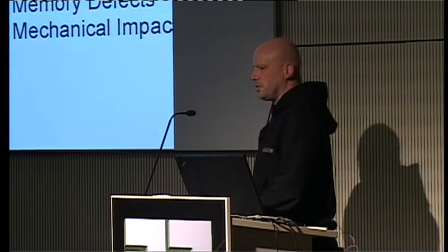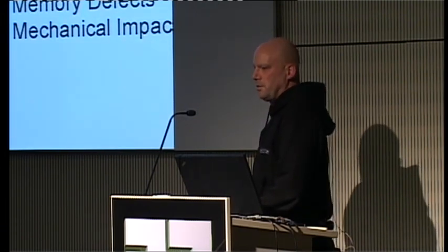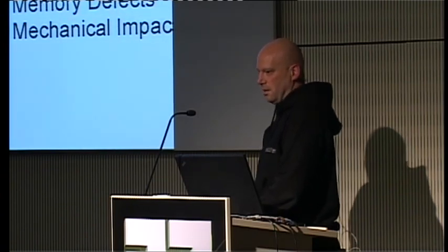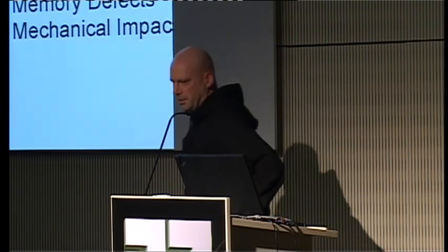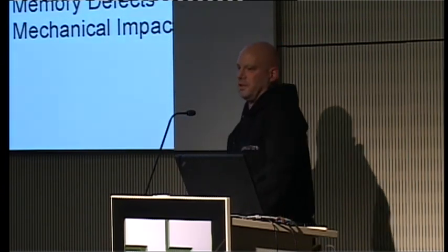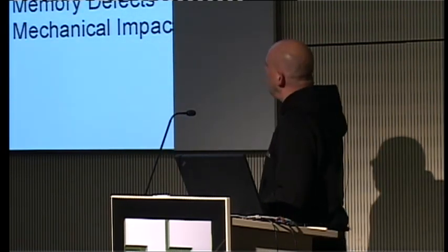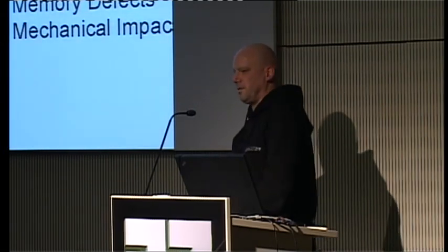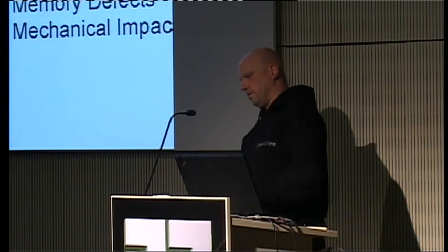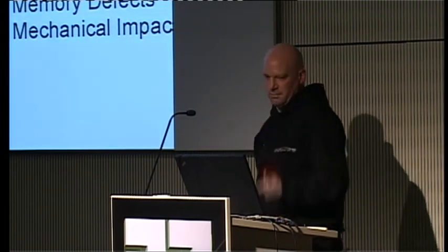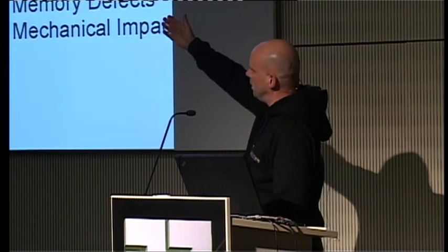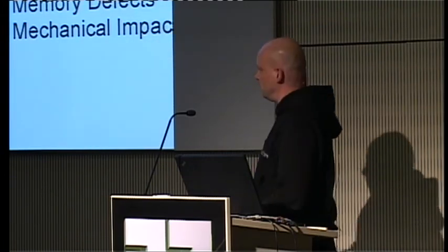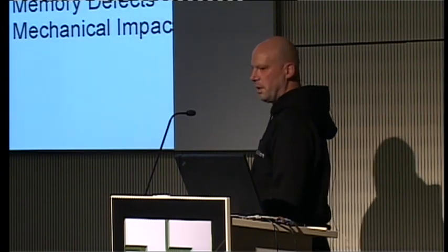Media contamination, meaning that, for instance, bearing fluid comes out of the bearing and spills over the platter, then of course you're done. Yeah, and then you've got all these external impacts like fire, water, and shock. But shock usually leads to surface damages or stiction or whatever. But you still have fire and water impact.